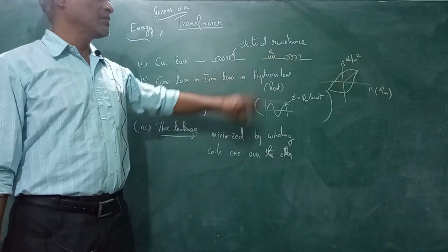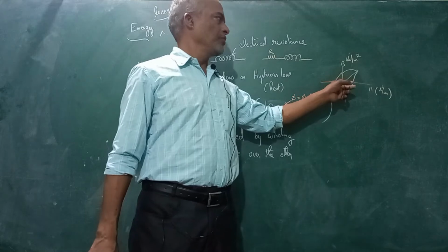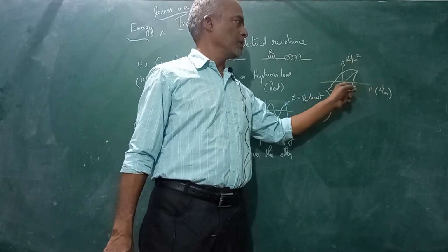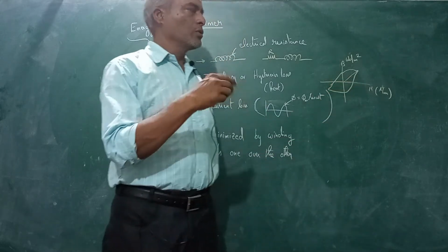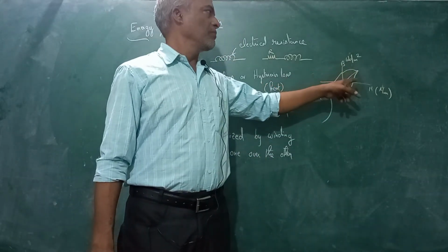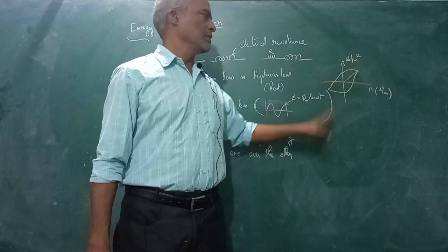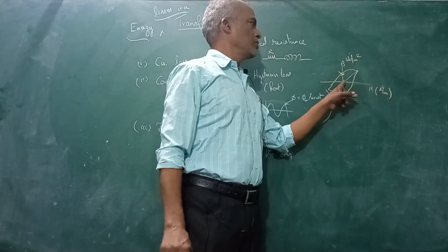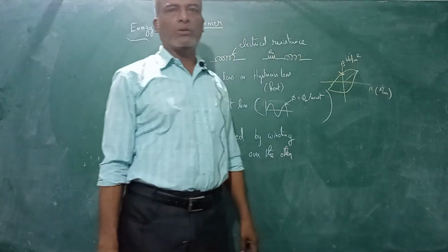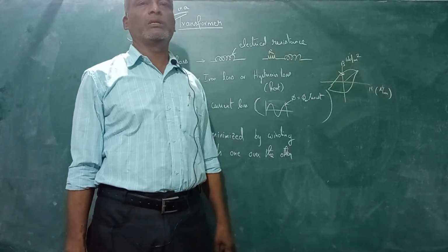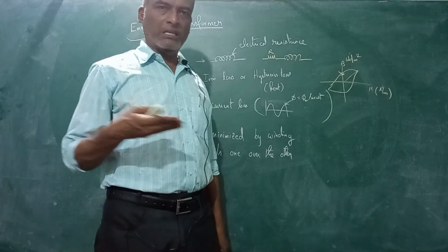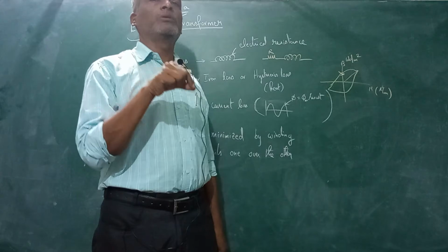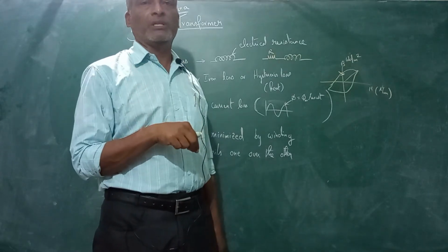And this hysteresis loss: if you plot the graph between H and B, that is amperes per meter, the current flowing through the coil, and the magnetic flux density, you will get a curve like this. One important point is, when I is equal to 0, the magnetic flux density is not 0. This property is utilized for recording in magnetic tapes, because even when the current is 0, the magnetic material is able to hold the information.